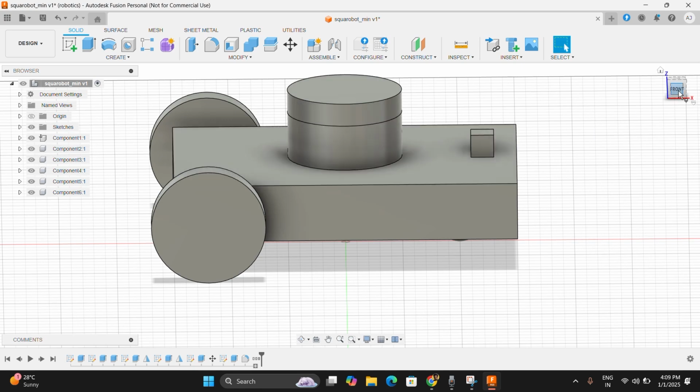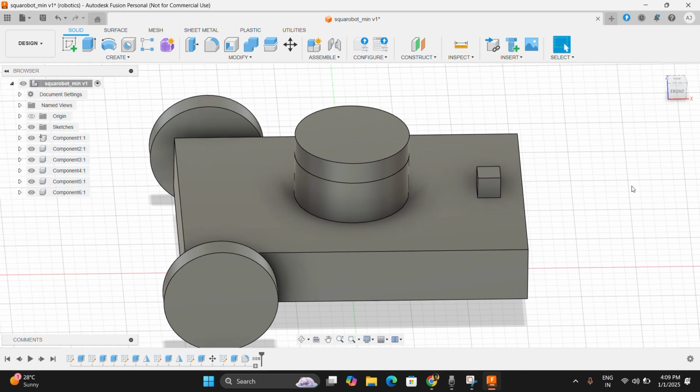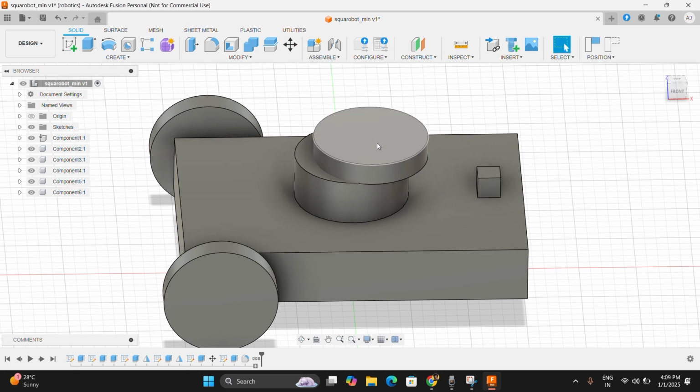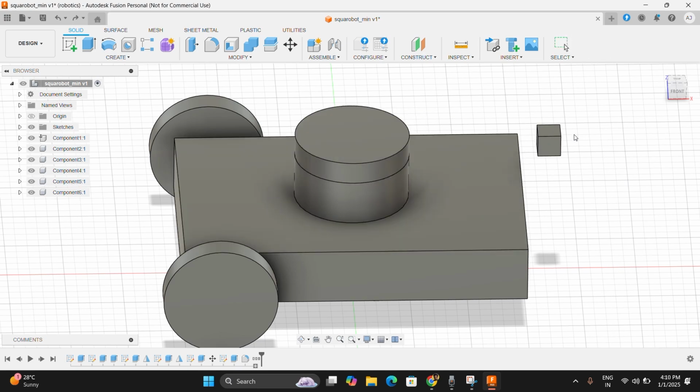Now we will add joints here. See, the problem here is now each of them is a different component. That is good. But if I drag it, it is moving. We have to make it fixed, right? It is moving. See, this camera is also moving. If I take this particular model and put it into the Gazebo environment, the robot will just disintegrate.